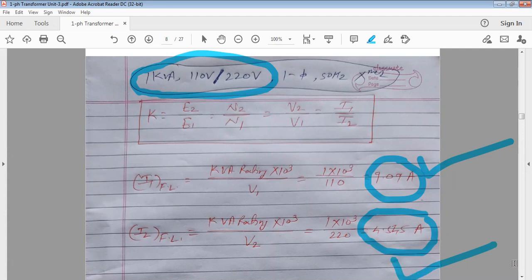You continuously increase the load, and if I1 and I2, either both or any one, reach this limit, then do not put further load on the transformer. Otherwise, what will happen if I pass current through the primary and secondary windings beyond these values?